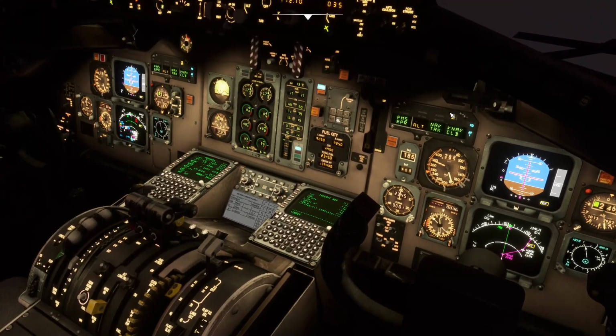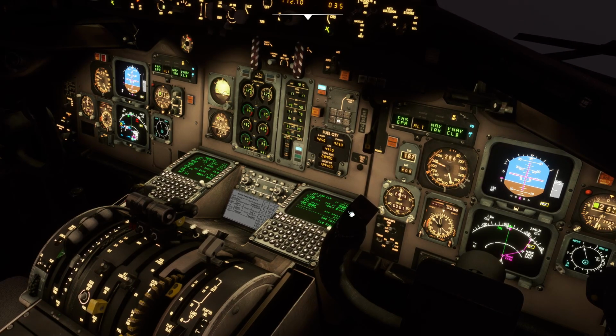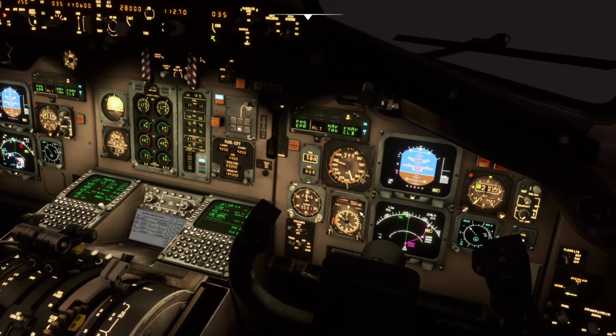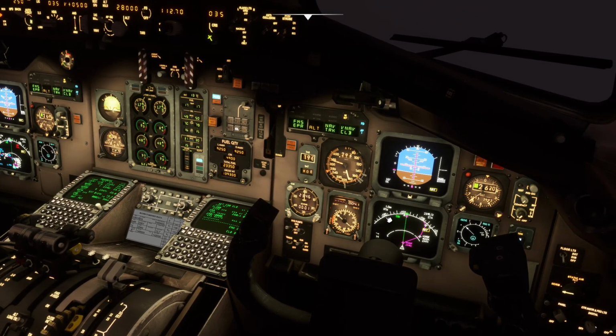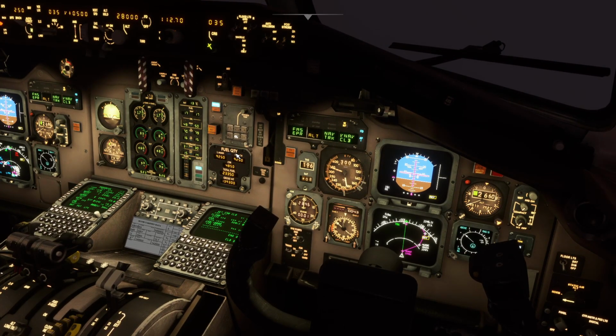Passing 180 knots, we'll bring the flaps in, slats stay out. I'll bring this to the climb performance page. And you can see we're doing direct enhance on the same SID, the Highland 6, just a different runway. Runway 4 right this evening.